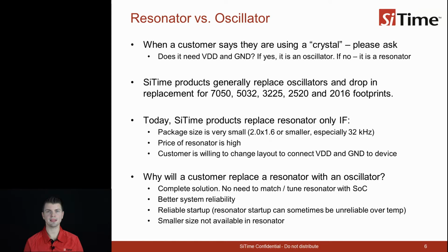However, there may be cases in which the customer wants to replace a crystal with a resonator or an oscillator. Some of the reasons have been mentioned before, and the key reason is to simplify the system designer's life and to relieve him from the burden of matching a crystal to the particular amplifier circuit integrated into the adjoining IC, thereby guaranteeing startup and proper operation.